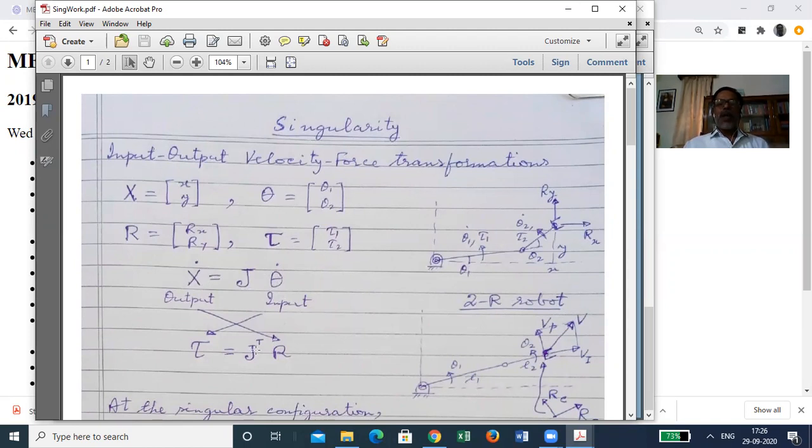And from some forces that the environment applies on the hand, and the hand has to counter by equal and opposite, you can find out suitable tau1 and tau2. Okay, and they are typically non-zero. I mean, it may happen that the force is such that only one of them can sustain it and the other torque input happens to be zero. That's a different thing.